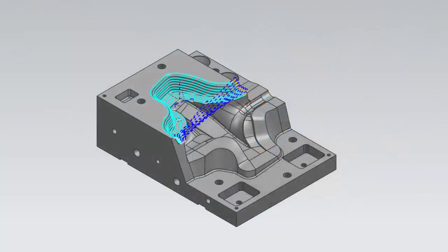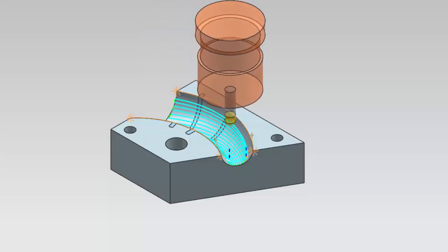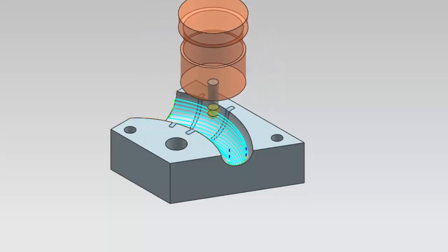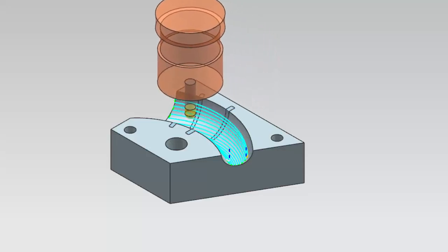Fixed and variable axis guiding curves are general-purpose finishing operations that work on many types of surfaces, including those not forming a grid. Using a ball tool or spherical mill, these operations create the pattern directly on the cut area without projecting. The cut pattern is created by constant offsets from a single guide or morphing between multiple guides. You can concentrate on pattern creation separately from tool axis planning since they are nearly independent of each other.